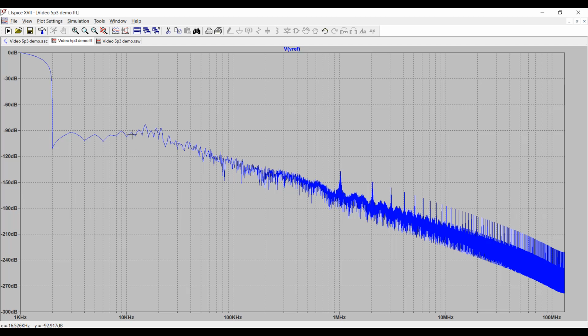You can see that our noise floor is very high. We get some screwed up images. The frequency binning, or the frequency resolution that you get here, is 1 kilohertz. You can see that the FFT couldn't process anything below, and the points between each bin in the FFT are 1 kilohertz apart, right? We've got a point here at 1 kilohertz, one at 2 kilohertz, one at 3 kilohertz, and so forth. This is terrible.